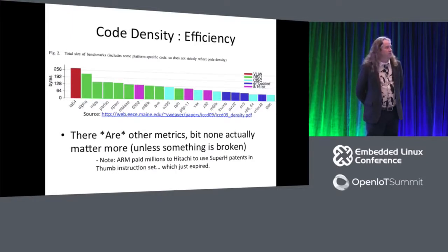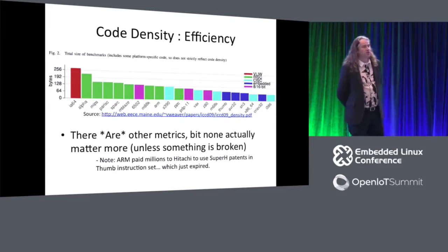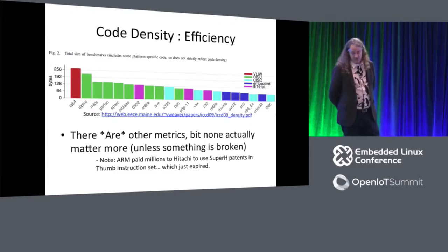It's a 16-bit instruction. So not only is the code density very high, and each instruction very CISC-like, because it came from the 68,000 space. There was some collaboration between Hitachi and Motorola at the time. But this RISC concept was folded in and incorporated into it. So the pipeline becomes very simple.